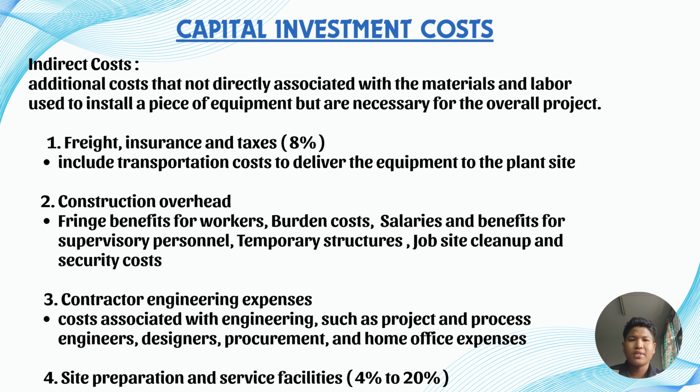And finally, we have the site preparation and services, which is a rate of about 4 to 20% depending on the condition of the site. This includes land grading, soil testing, drainage, and setting up the utility services such as water, electricity, and the access road.